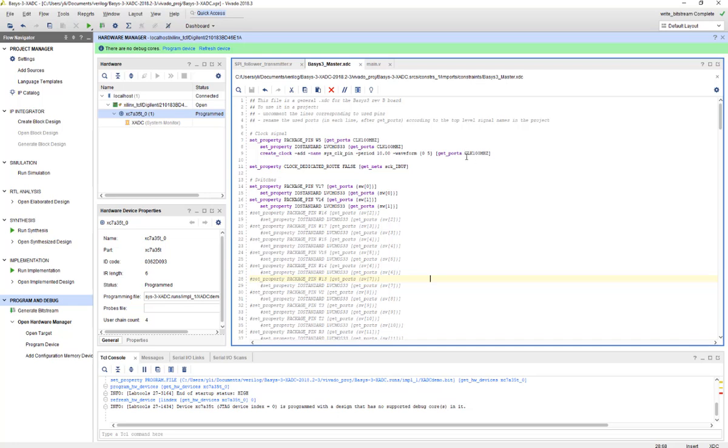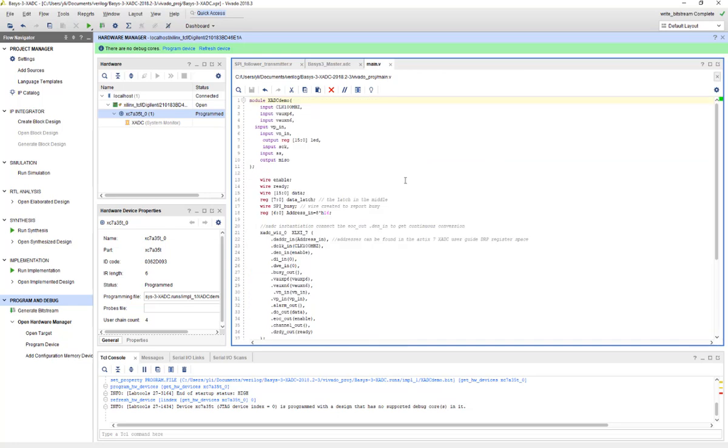Remember that this clock's name is different from CLK. They use CLK100MHZ. So in your top file, you have to use that same clock name, CLK100MHZ. So LEDs have to be declared. Eventually, everything was sent to the LED for display.